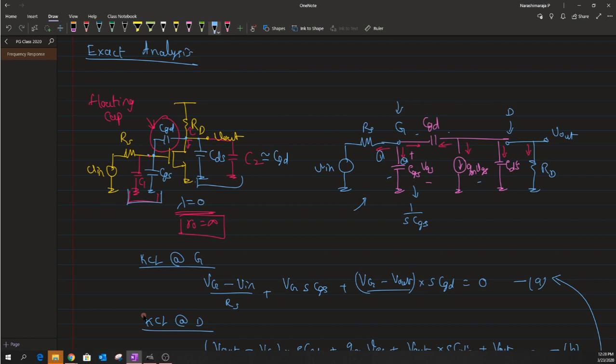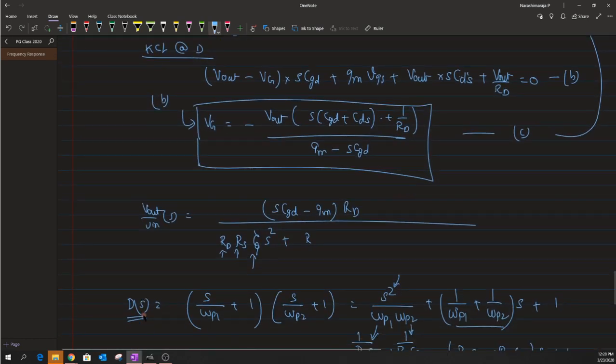combined as a combination of two at a time. Okay, so due to which each of these capacitors will actually share with the other capacitance, two capacitors at a time. And based on this, one could write the factor of eta to be equal to CGS with CGD and CGS with CDS. And again, what is left over, the one combination that is left over, is the combination between this CGD and CDS. Okay, so hope that you're clear.